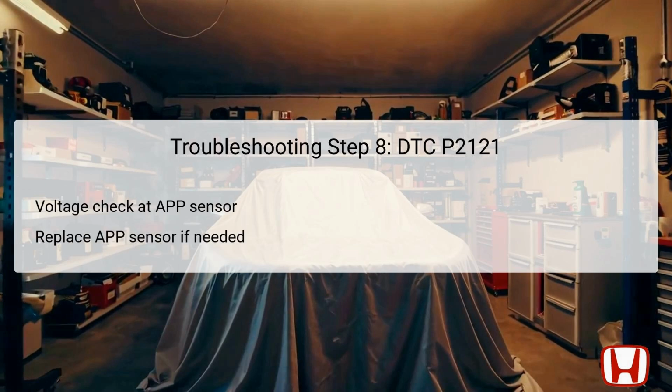In the eighth troubleshooting step, the investigation shifts back to the APP sensor itself to determine its operational integrity. The technician will turn the vehicle to the off position and then disconnect the APP sensor connector to set up for voltage measurements.